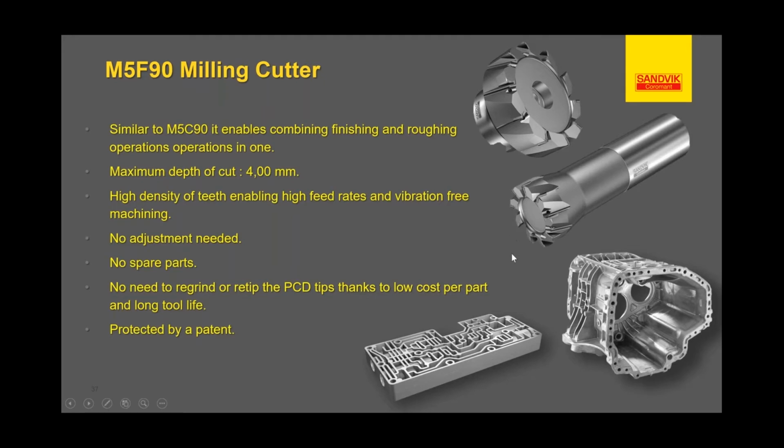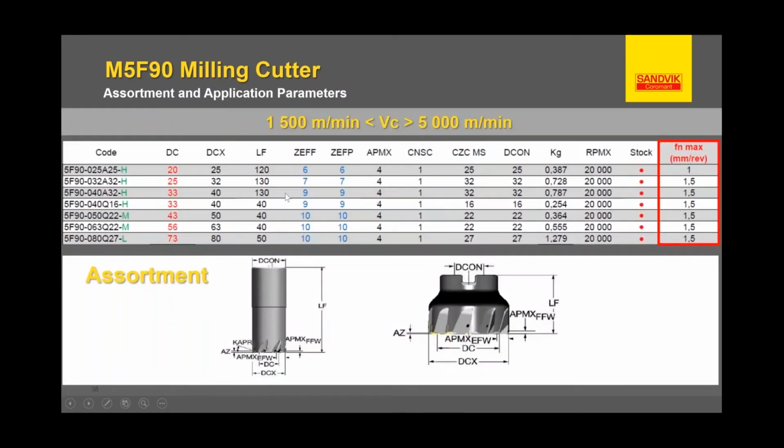But they're designed for thin wall parts and smaller diameters, maybe smaller machines with really high RPM, like even a Brother machine that has real high speed, something of that nature. We go all the way down to 20 millimeters on the cutting diameter. The biggest one is at 73. And these are an on-the-shelf solution. They're available, not custom engineered.